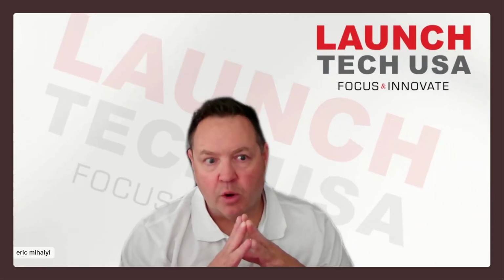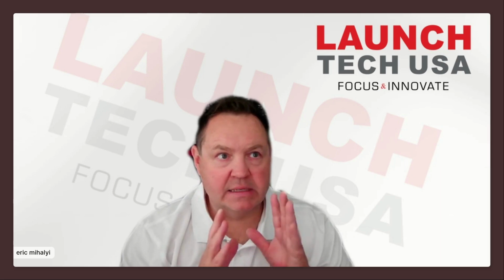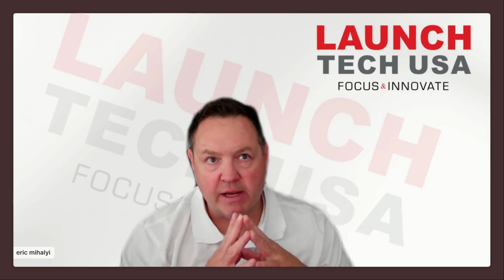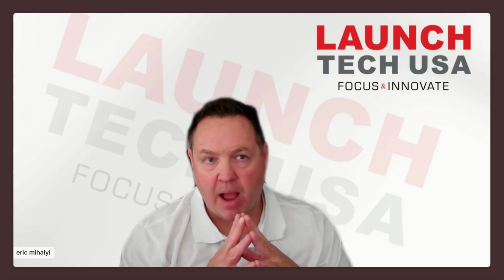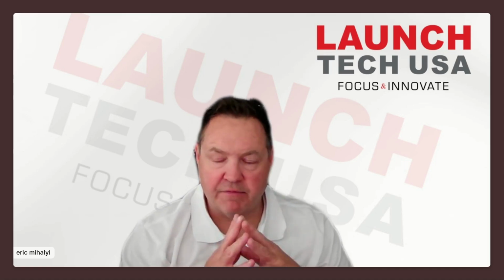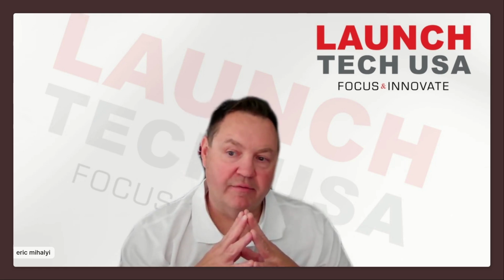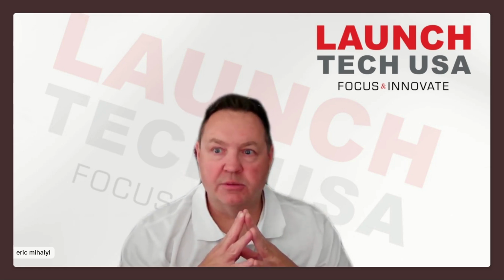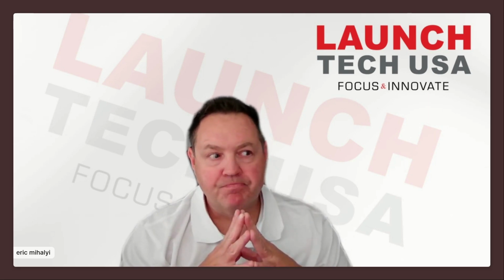So a lot of normally aspirated engines are going to fall into that 90 to 95% efficiency rating when new. They can get a little worse as they age and get high mileage. But if you're looking at an engine that has a 68 or 70% volumetric efficiency during a test drive, I need to look at an engine mechanical situation, assuming my math is reading correctly.